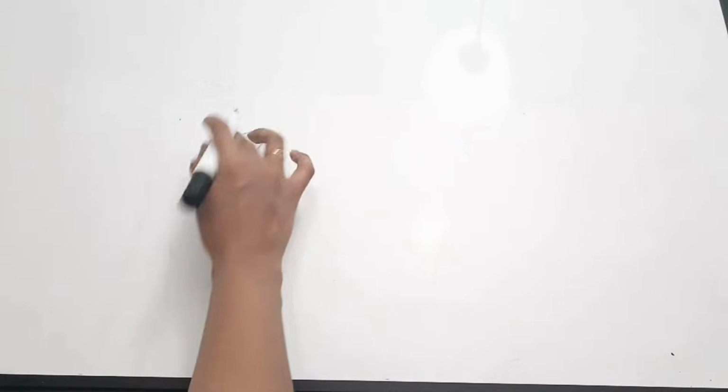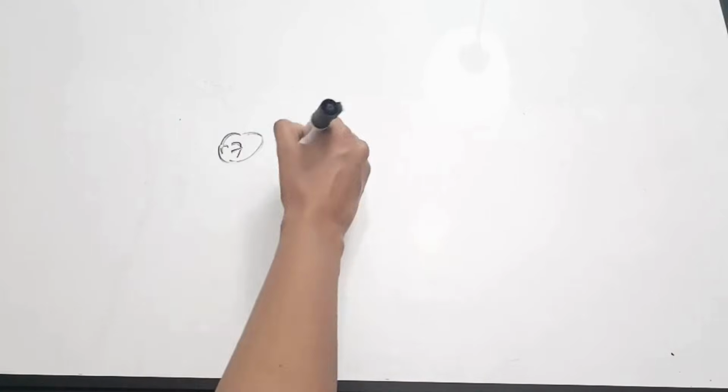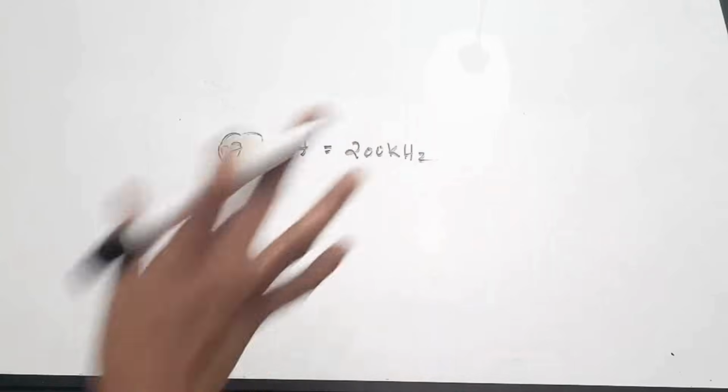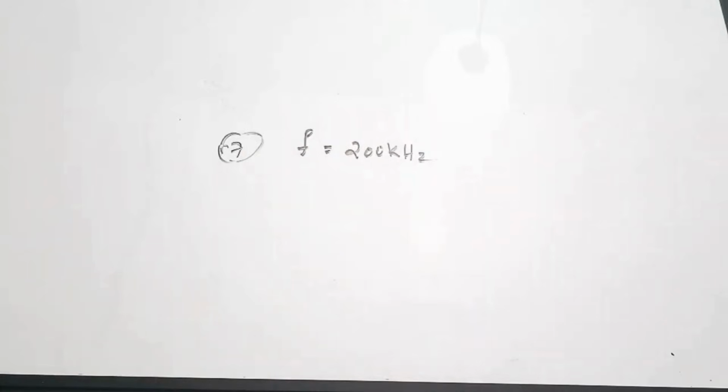So the frequency F is equal to 200 kilohertz. Now, we are designing a serial shift register. So for the case of a serial shift register, the bits are entering serially, meaning 1 bit at a time or 1 bit in 1 clock period, right?